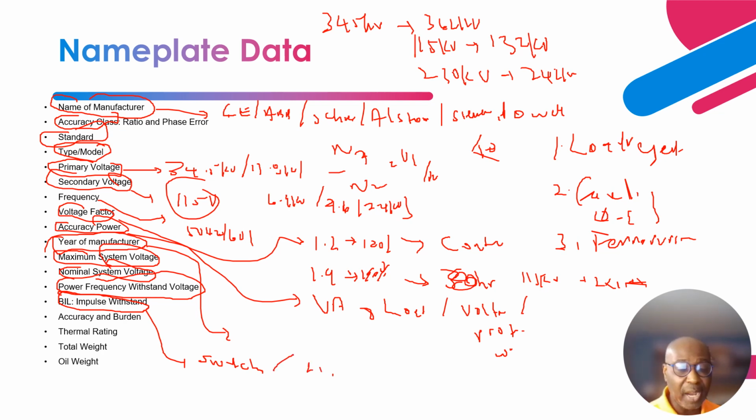That lightning strike can induce very high currents, and also DC offsets, and based on the configuration, especially the Y grounded, can create paths for these lightning currents. And so the insulation system has to withstand that.